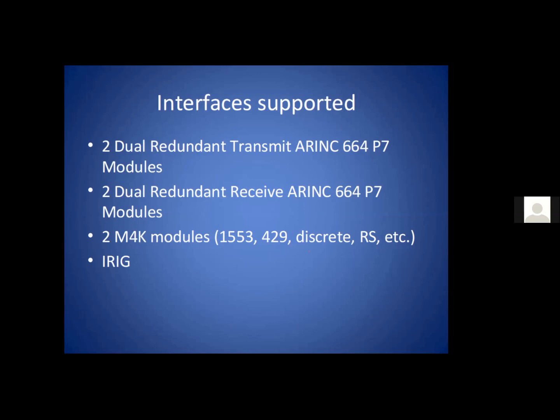Now, IRIG time itself only gives you precision to the nearest second. We add to that our own microsecond counter. So every second that comes in, we start counting microseconds. That gives you accuracy and precision to the nearest microsecond.